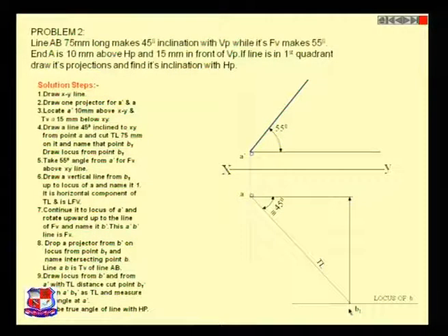Similarly, draw a perpendicular line from the point number B1, naming it as point number 1, extend it till this point, which is called B2 dash. From the B2 dash, what you will do, A dash to B2 dash as radius, A dash as center, draw an arc till it intersects with this 55 degree reference line.